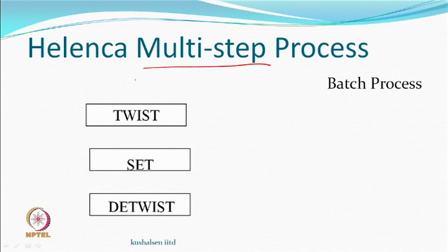So, there was a process in which you had multifilament yarn, you would twist them starting from some package, and after twisting you go through a next process called setting. That is, you must set the twist. Now, how you set would depend on what type of material it is, whether it is a thermoplastic material, a non-thermoplastic material or whatever. Let us say it is a thermoplastic material.